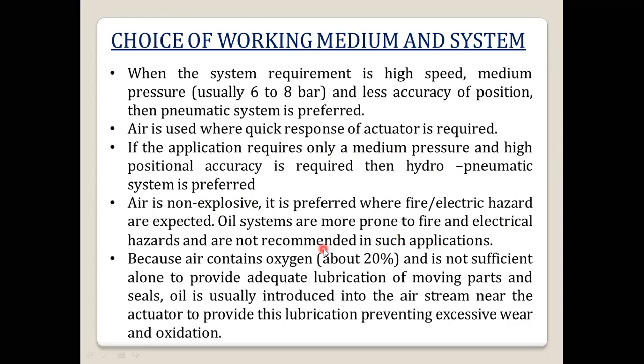So they are not used in such applications. Wherever electrical hazards and fires are present, we will not use hydraulics, that is oil. Air contains about 20% oxygen, and it is not sufficient to provide adequate lubrication of moving parts and seals. So oil is introduced into the airstream near the actuator to provide the lubrication.